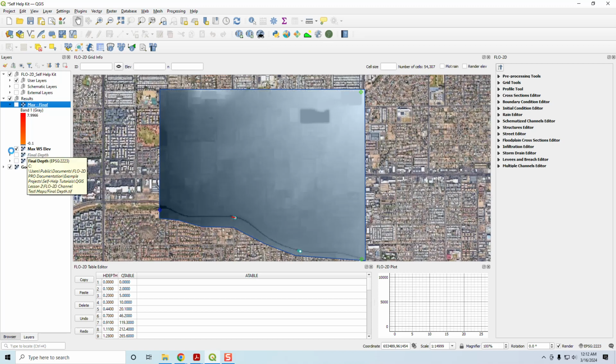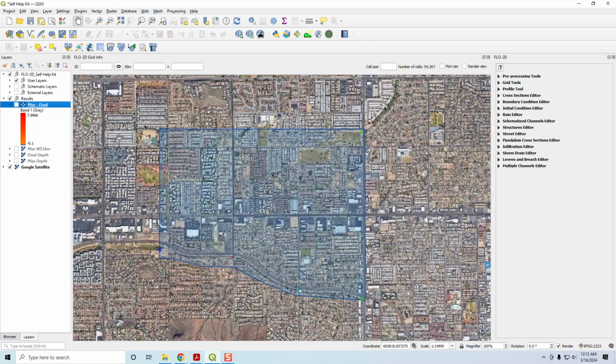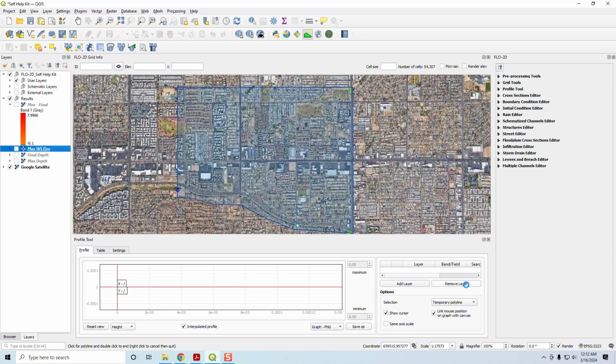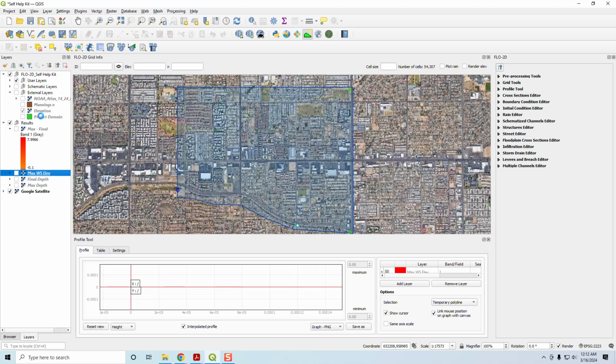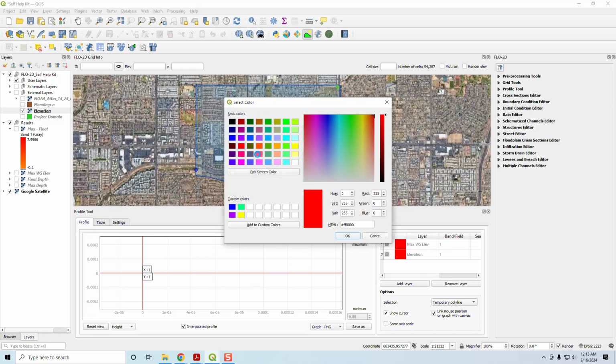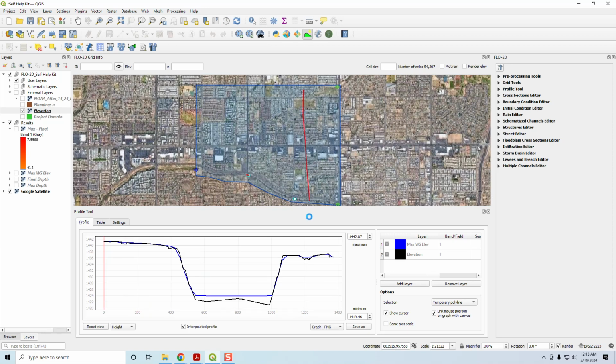Water surface elevation. Now let's take a quick look at one thing you can do with another plugin called the interpolation tool. So I am going to shut these two off, and I'm going to add this layer here, and then I'm going to add our elevation layer here. And then I'm going to expand this window so that I can turn this one to blue and this one to black. And then I will draw a profile, some spot where there will be a difference.